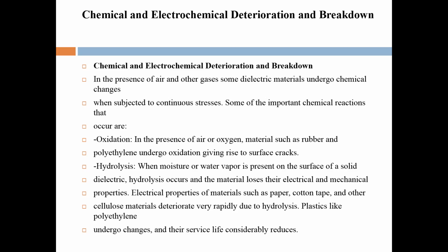What happens? Cracks are going to be produced due to the presence of air or oxygen, and the oxidation takes place in materials, for example rubber and polyethylene. Then at this time, surface cracks are going to occur on the solid dielectrics.